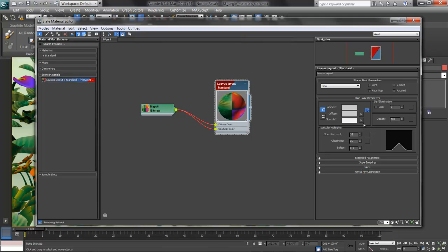What I'd like to do is get some different materials established for the different plants, reusing this texture. And this is a workflow we'll use in a game a lot, where we see one texture, or one image that's part of a material, that works for many different objects in many different ways, although the objects themselves have different ways of shading regarding the light. What I'll do here is make some new materials, and get their shine set, and then connect that map to it.